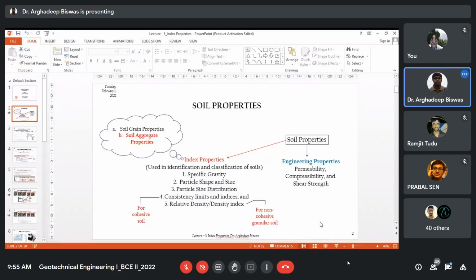Okay, so that consistency or degree of firmness has some relation with water content, because the more the water content, the softer the soil body, and it will be easy to provide some shape to that particular soil body. The less the water content within the soil mass, the harder it is to crumble or break it, and whenever you try to remold it or give some shape to that body, it will break or crumble. So that qualitative measurement, not in the true sense quantitative, I'll take up that part. That indication is called the consistency limits, the amount of water present in that particular body, and the corresponding different indices that we have derived from those limits.